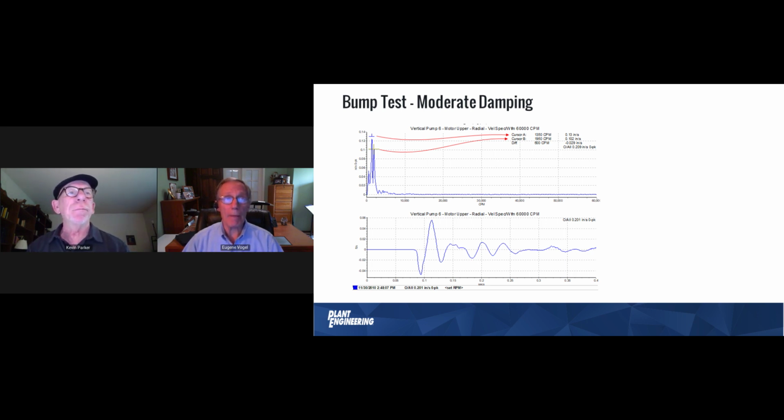Well, imagine that you have a piece of reflective tape on the shaft. And let's say our vibration is at rotating speed. The machine is out of balance, so you have one cycle of vibration for every one rotation of the shaft. And I have a piece of reflective tape on the shaft, and I have a photo tach, a little laser pointer that every time that tape goes by, puts out a blip, blip, blip. So the time it takes to get from one blip to the next blip of that reference pulse pickup is one revolution. So if that time is, for simplicity, say 10 milliseconds to make one revolution.